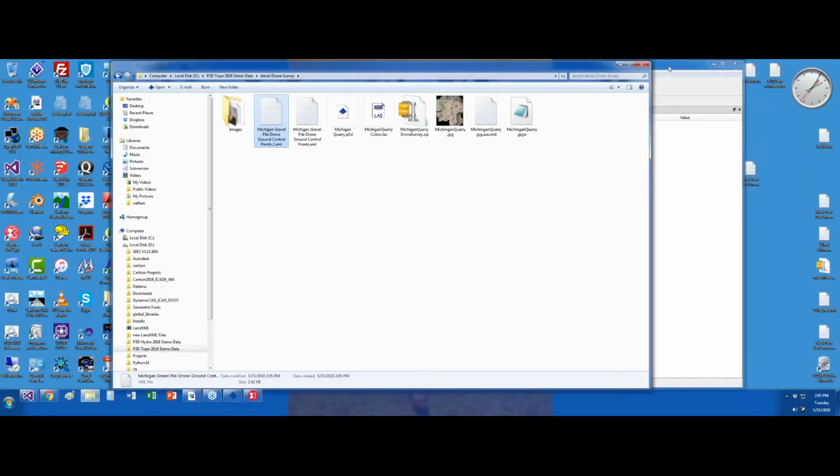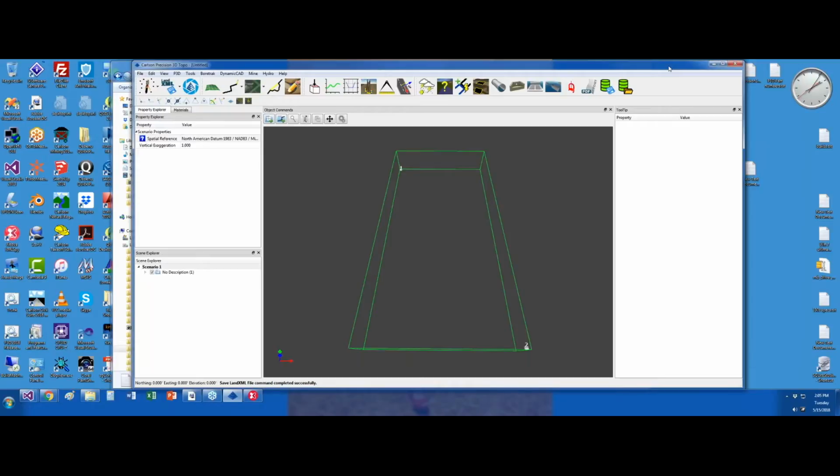When you see Ben start to work with the LandXML file, you'll notice that he just drags and drops and things happen automatically. Once you set up your coordinate system and your units of measure, or your projection system, here in P3D, that's the only time you have to set it. For the rest of the workflow, we automatically read the units of measure and the projection back out of the LAS file when Ben's done with it. So we try to make that just as easy as possible.